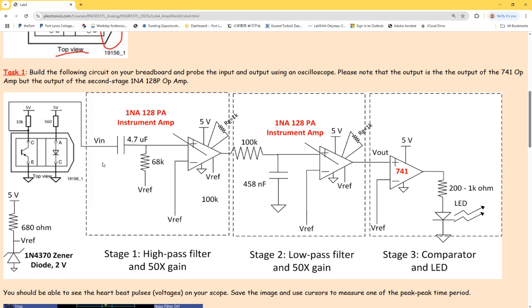So you can see for most of the amplification circuits and filtering circuits, you have to use a high pass filter first, and then you bump the AC signal to its desired DC offset. That's the main thing I want to teach you guys. You know, a lot of people don't know how to do it.